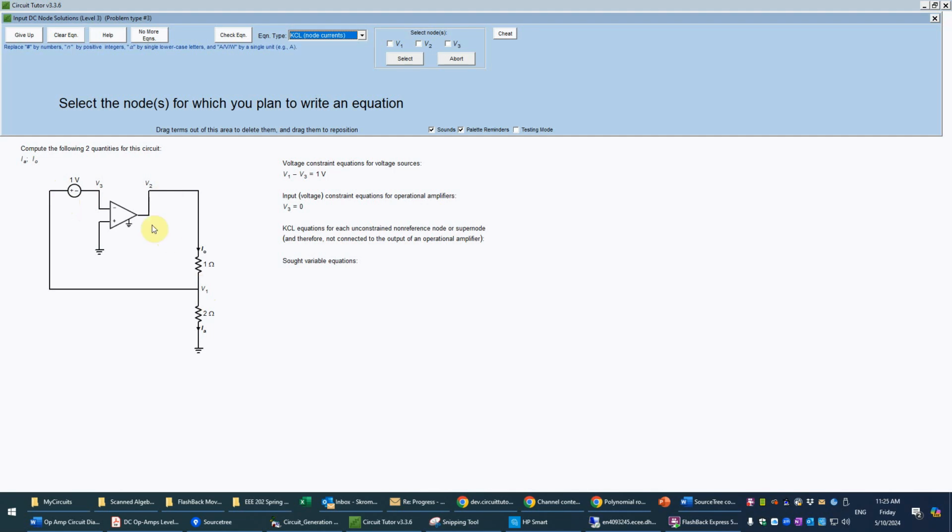So if you reflect on what I told you about the op-amp, it has an internal voltage-controlled voltage source connected to the output, the other side connected effectively to ground, although there's no real ground connection in the op-amp. There's really just plus and minus power supply connections, which are not shown here explicitly. Because of that, this is like a voltage source, the output, and we don't know its current. Therefore, we cannot write a KCL equation for node 2.